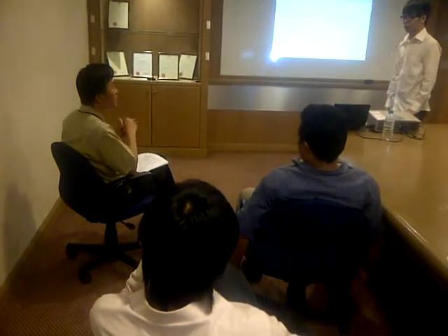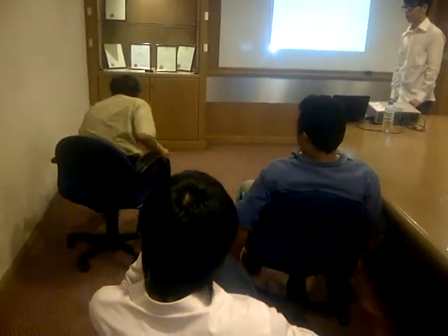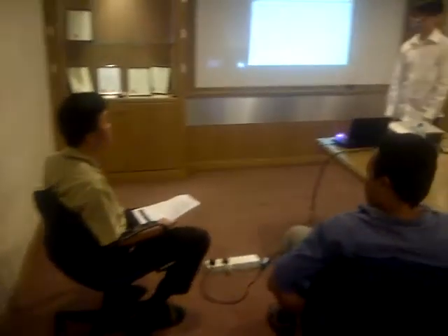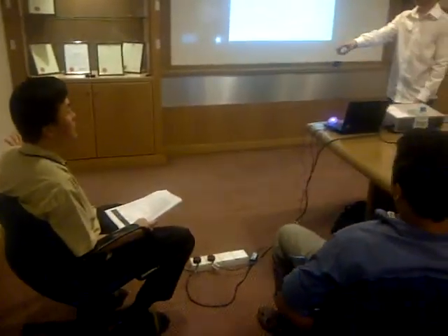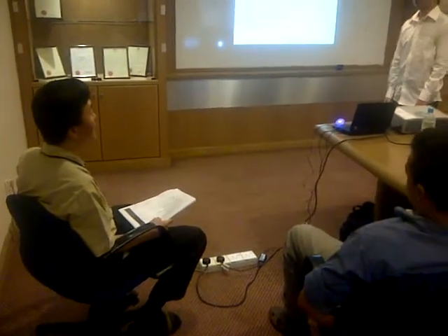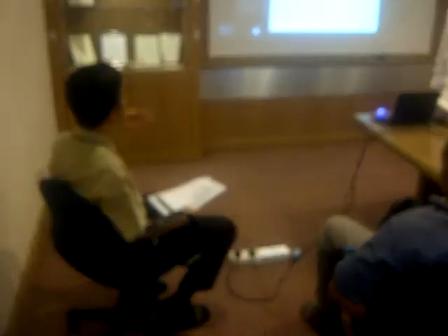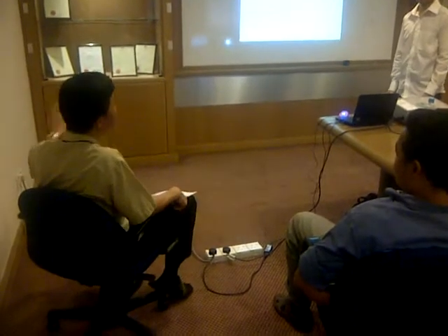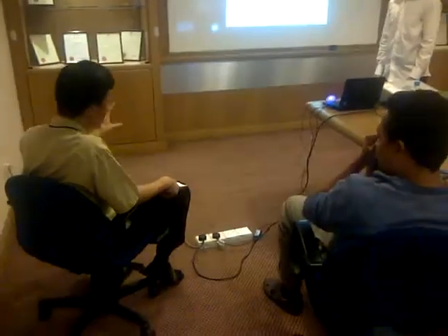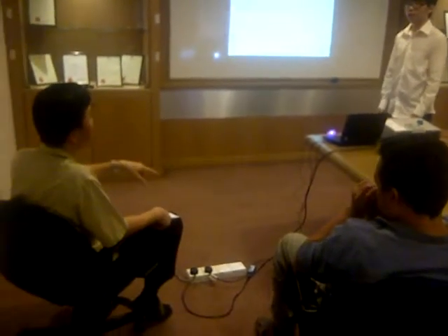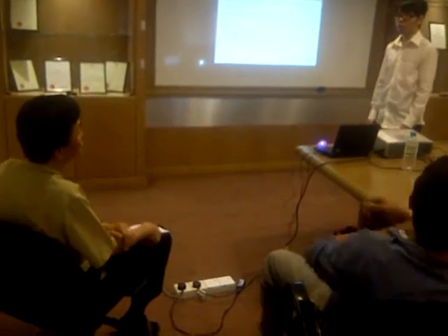So oversized. Very importantly, when we assume load 250 watt, this socket can deliver 13 amp, because this is the standard 13 amp socket outlet. So this switch socket outlet can give you 13 amp without any problem, because I assume according to the use. So if 13 amp multiplied by 240, how many watt? 1500. Yeah. Let's say 1500 is the maximum. But 1500 can produce a lot of work already. Even though you have multiple computers connected to it, you will never reach 1500.